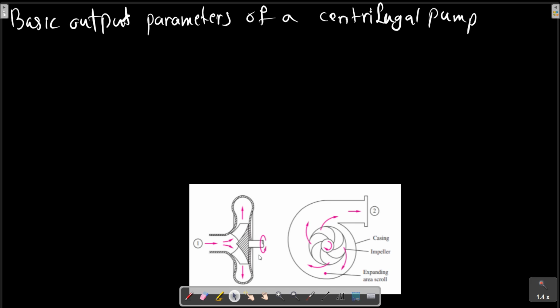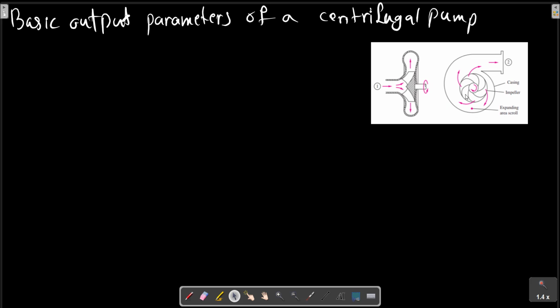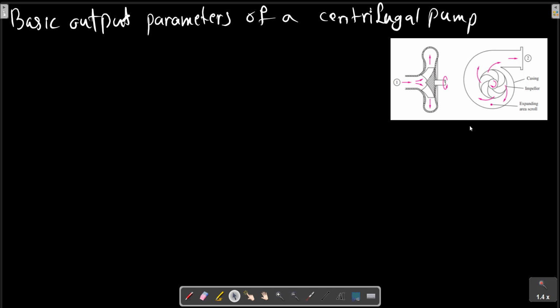A centrifugal pump is shown in this picture. Assuming a steady flow, the pump basically increases the Bernoulli head of the flow between point 1 and the exit of the pump, as shown also in this picture, and point 2, neglecting viscous work and heat transfer. These changes are denoted by H.